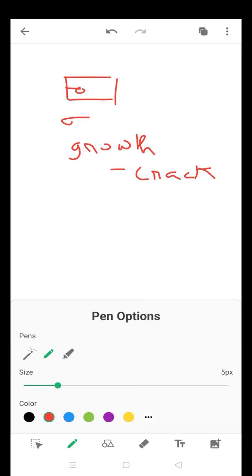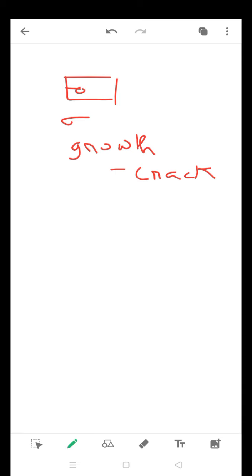Now we will concentrate on the factors at the crack tip which actually lead to the growth of this crack. Or, what is the amount of stress that the material may withstand before the crack can grow? Now, according to Griffith, he actually laid a criterion. It's called Griffith's cracking criterion.